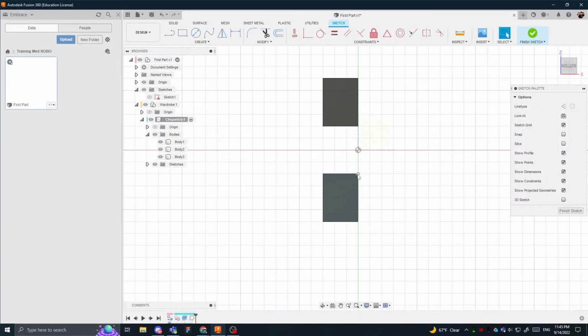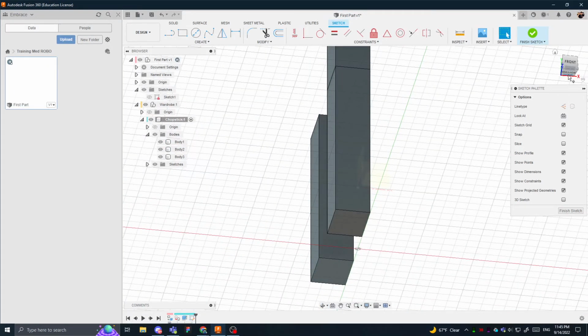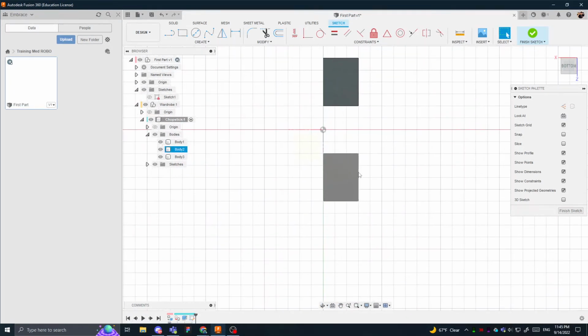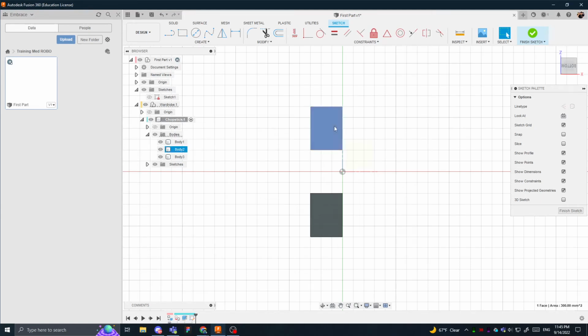When I put a sketch on here, I can click on the corners, and it recognizes them. However, sometimes it won't recognize it, and sometimes we have to use a projection. A projection is if you had to look at it from this orientation. Like, let's say I want to project this face. Then it would put me straight on, directly head on to this face right here. Be careful, when I rotate it, it actually changed the direction. So this is the same one. I would have to project it so that those edges show up and I can reference them.